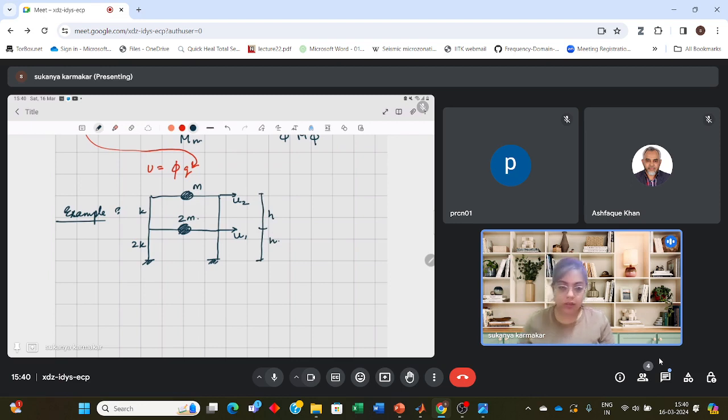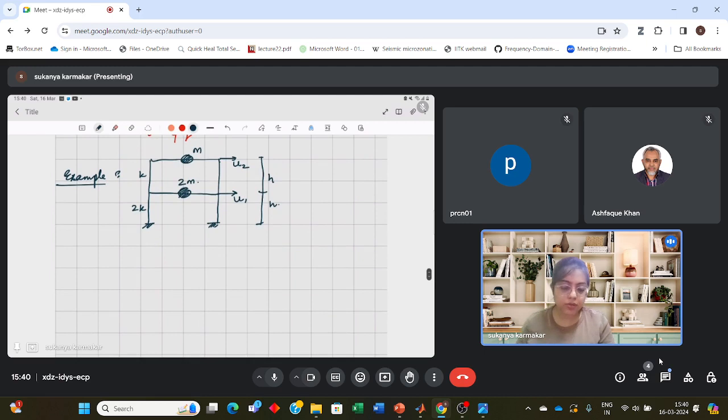First, we'll find the natural frequency and mode of the system. And this two-story frame is idealized as a shear frame. This means the beams are assumed to be rigid. That is, they are not actually rigid, but I should say E B is equal to infinity.